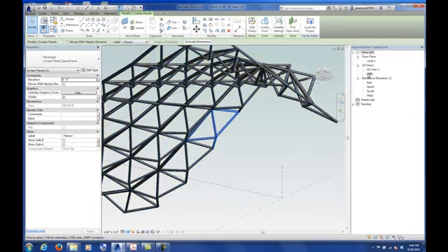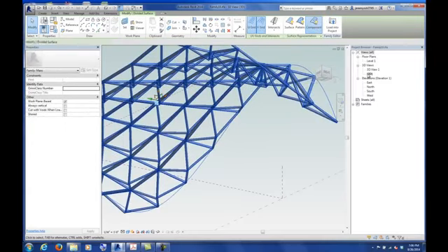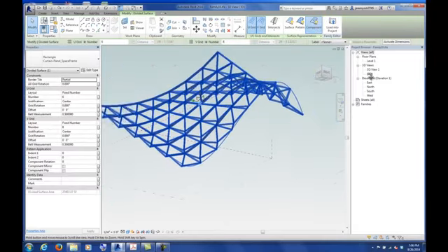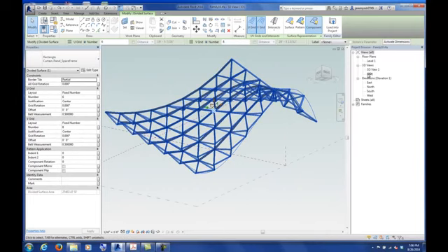I can select this divided surface. Look to the left on the screen here. Under properties, when you select your divided surface, you have other options where you can change the pattern application. Under pattern application, I can indent, but I'm not going to get into that.